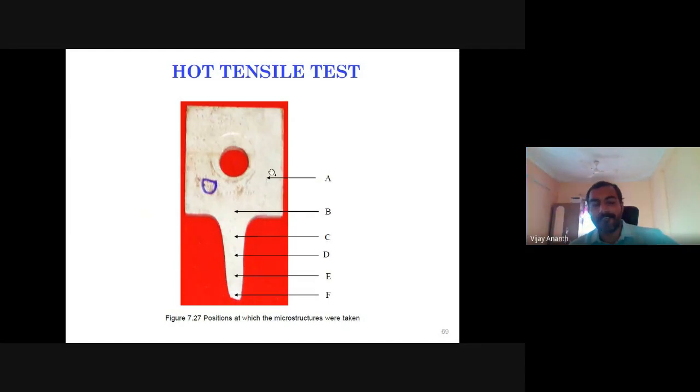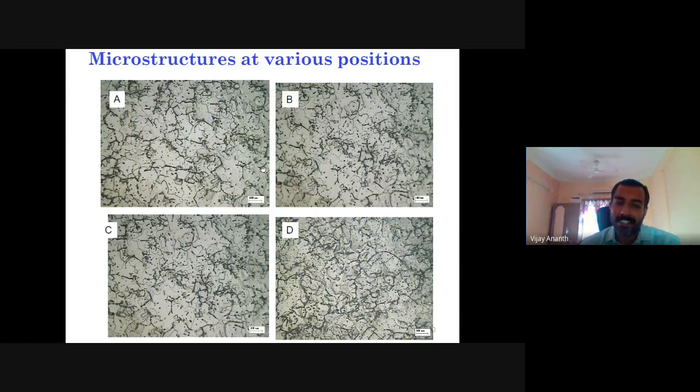And we'll see how this microstructure is changing through superplastic forming, right? So this is some micrograph. These are all the grains, as well as in the grain boundaries only we are having the silicon carbide particles, as well as second phase particles also there, the Mg2Si like that, right? So these are the grains, right? And this is in the gauge region.